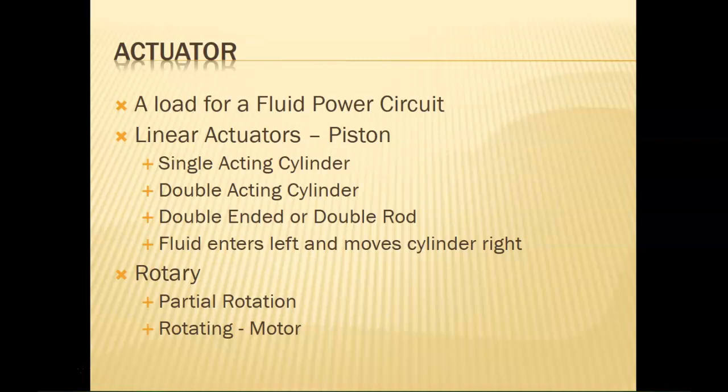So the motor is this guy right here. The little pneumatic motor. And he's able to fully spin 360. And when you put air to him, he just does not stop spinning. Okay? So this is what we mean by a pneumatic motor. And no, they don't generally put out a lot of torque. When you're talking hydraulics, those things put out a lot of torque. That's what it needs to do.